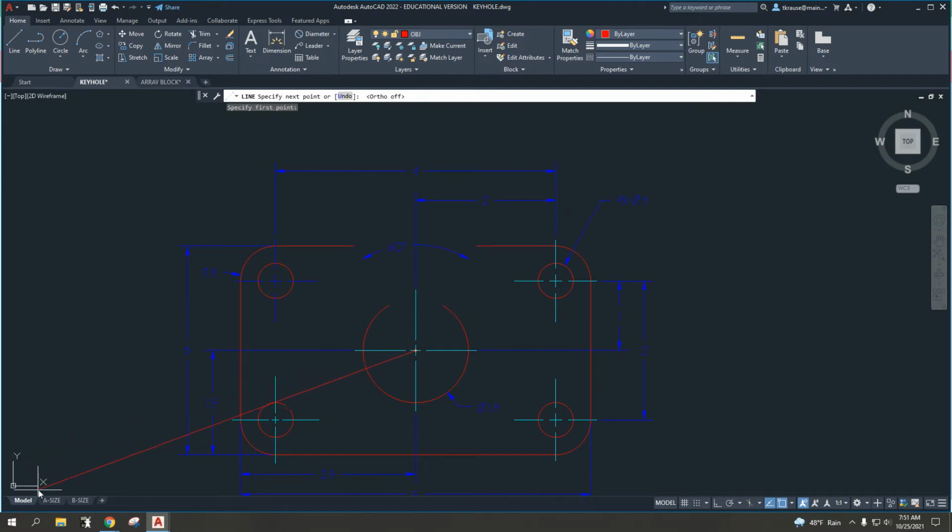Down in the bottom left hand corner, you'll see we have an XY representation. So horizontal distances in AutoCAD is the X, vertical is Y. Technically, if we were looking at a piece of graph paper, here is our zero line going off to the right. And then as we go up, we're going into positive Y, and we're in positive X to the right. 90 degrees, now we're going up. 180 degrees would be horizontal out to the left. Let's see, 180 plus 90 is 270. So 270 would be straight down. And then all the way back around is 360 degrees, which is where we started at 0.